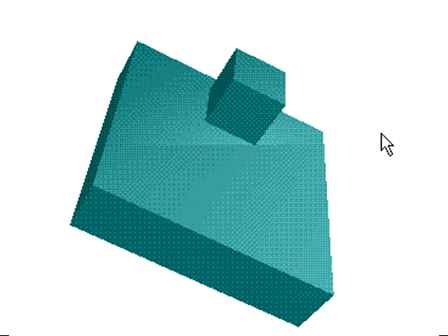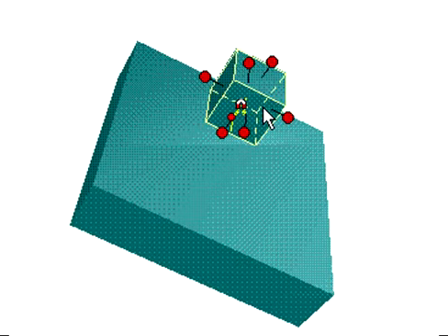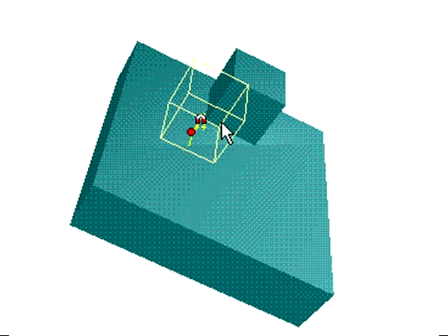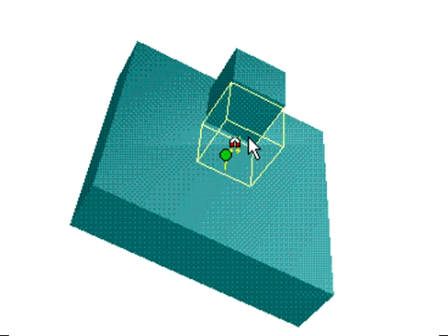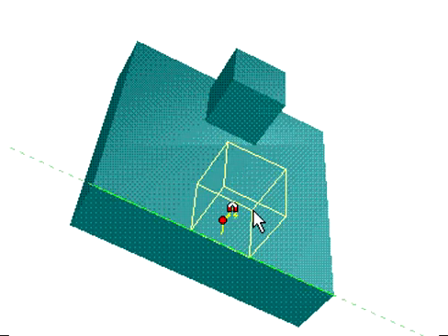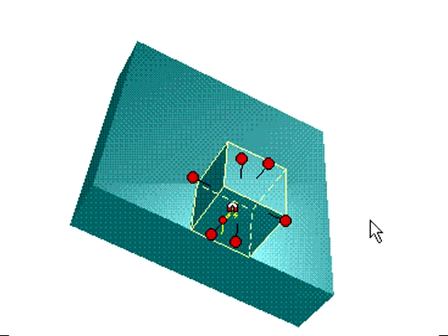Use SmartSnap to help you position the IntelliShapes in your model. First, select the shape you want to move. Then hold down the Shift key and drag the selected shape. As you drag, watch for the visual cues from SmartSnap. A green dot indicates a center point. Green lines appear when two edges are aligned.